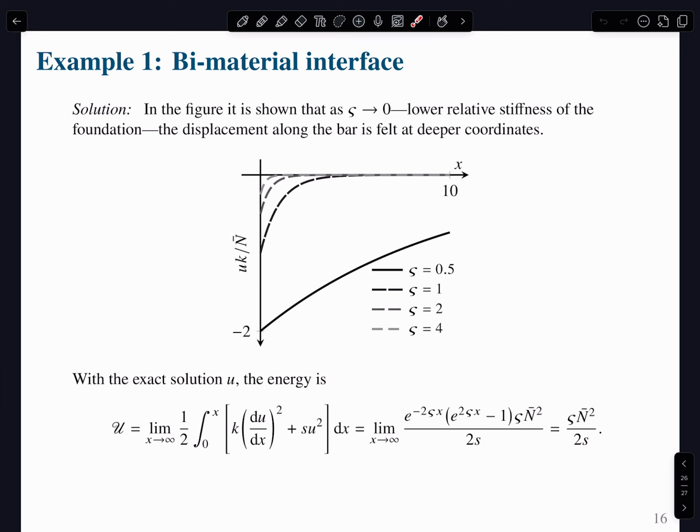You can put the exponential function in the element. There we go. Enriched FEMs. Yeah, that we can do. We can add an exponential function. We know the exact solution of the problem. How about we just add the exponential function to the approximation, right? The Galerkin method is going to tell us whether it is good or bad. If it makes the approximation worse, it's going to assign a zero coefficient, right? If it is good and the error is reduced, then it's going to assign a non-zero coefficient.